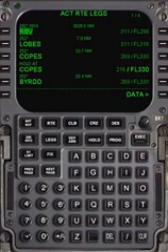Topic: Navigation database. All FMSs contain a navigation database. The navigation database contains the elements from which the flight plan is constructed. These are defined via the ARINC 424 standard.